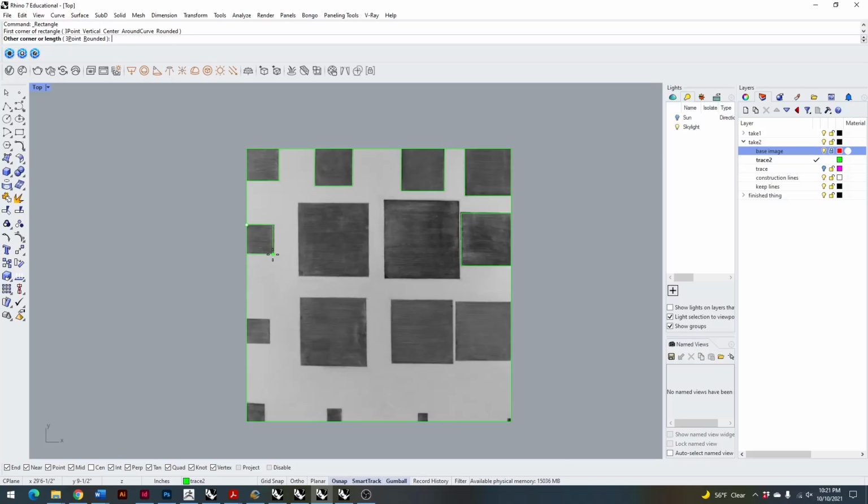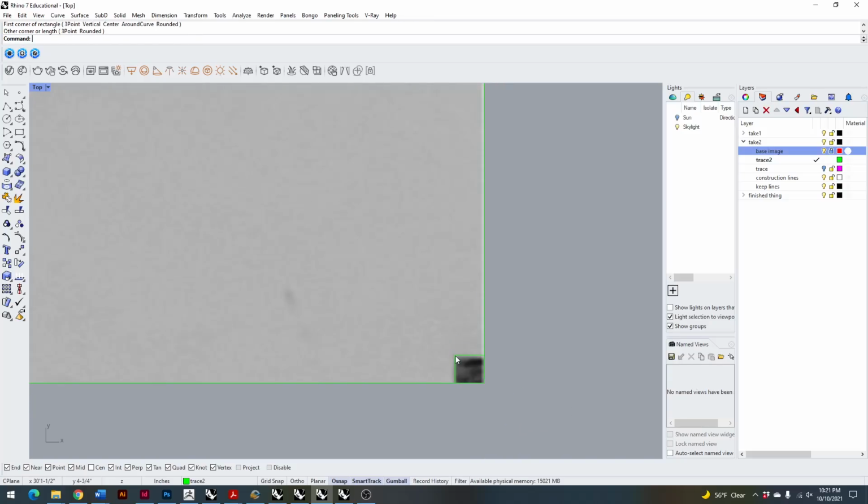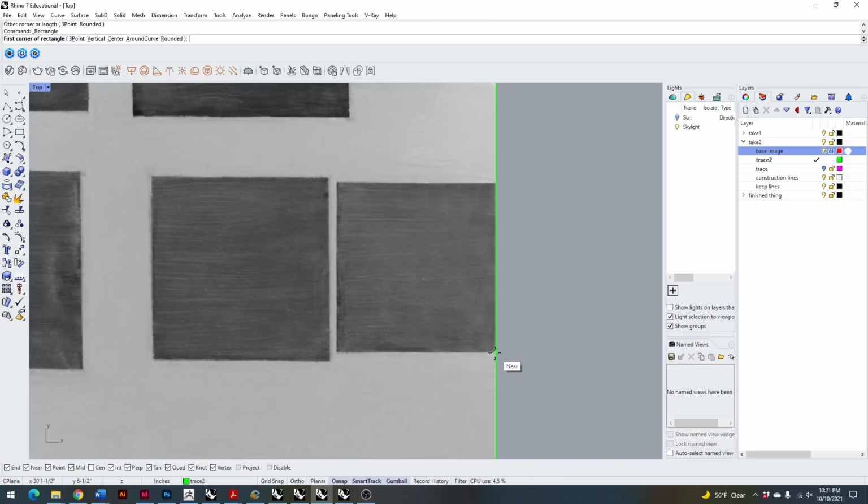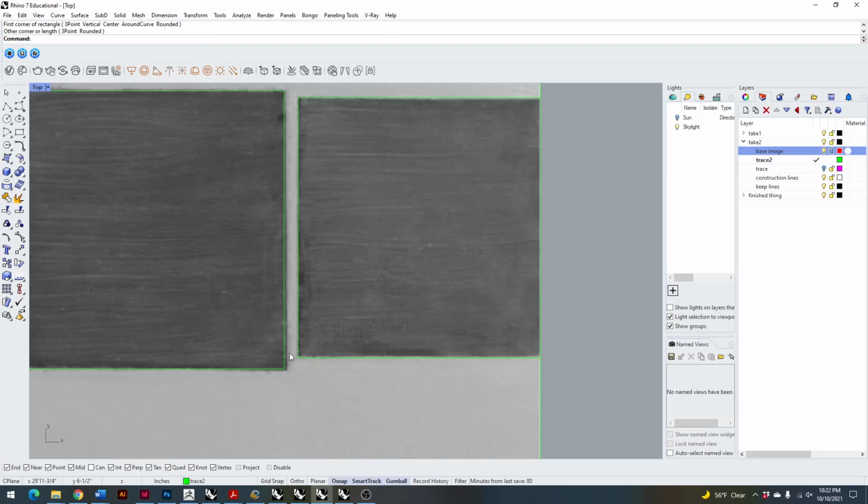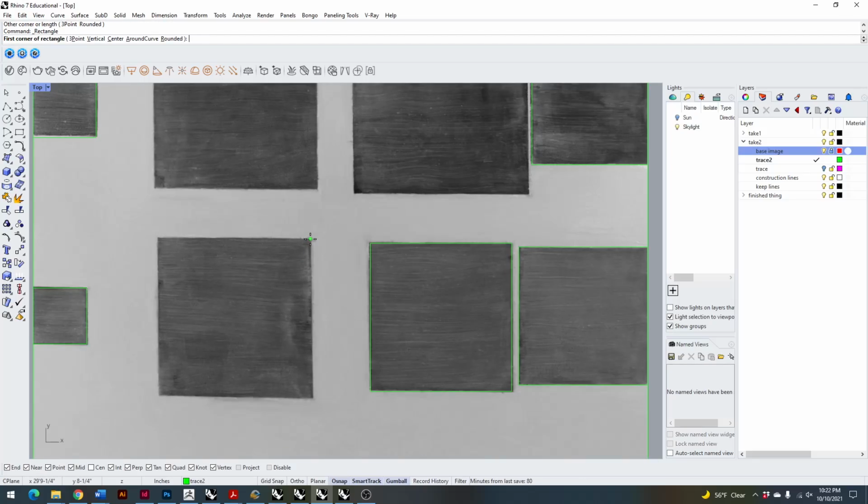I might call that a solid void relationship, and this is the lens I'm going to use in order to begin constructing elevations off of this image. And if your snaps get a little too tight, you can zoom in. And again, I'm missing edges, but it's okay because it's a trace. It does not have to be perfect.